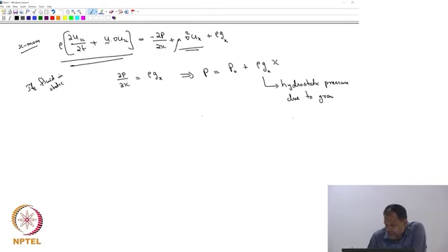gravity. What does this expression tell you? Siddharth Singh, what does this expression tell you when you look at it? How do you interpret? One is that pressure varies linearly with height. The fluid is not moving, still there is a pressure gradient, right, because of the weight of the fluid. So it's as if there exists a pressure gradient that supports the weight of the fluid, and that's what gives rise to buoyancy forces and so on, right?